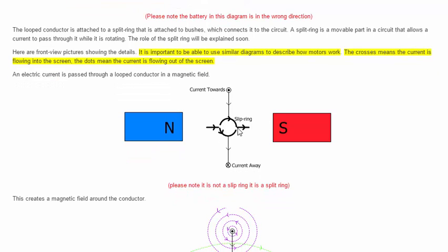Okay, now as it's being pulled up, at some point, and now I hope this sketch will make sense, these are the slip rings. So here's what the current does. The current in the outside circuit is coming in here, making a connection here, and then coming there. It can't go there. There's a split. That's why it's called a split ring. So it goes down here, then it flows into that loop, flowing away from me, and then it's coming back towards me and in here.